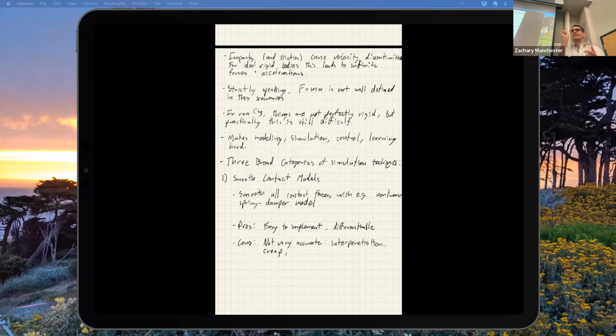So you end up having to take really, really tiny integrator steps, use fancy integrators. This is one of the reasons a lot of these simulators end up taking 2 kilohertz time steps. It's because if you try to make the contact more realistic, the ODEs get too stiff, and then your Runge-Kutta method starts to barf at you without taking uber tiny time steps, which is very inconvenient also.